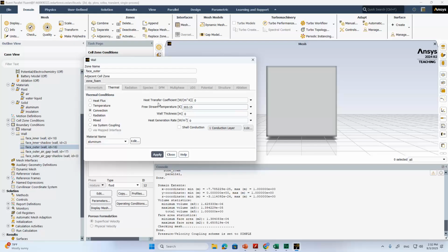Here you also have to give the heat transfer coefficient, that is the convective heat transfer coefficient or convection coefficient. You have to find such values with some hand calculation, with equations you can find from your heat transfer textbook. Roughly speaking, such convection coefficient is at the magnitude of 10. But it depends on which surface you are talking about. The convection coefficient at the top surface typically is different from that along the vertical surface, and is definitely different from the convection coefficient at the bottom surface.